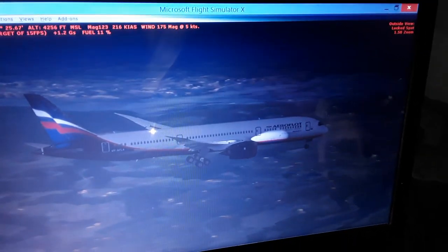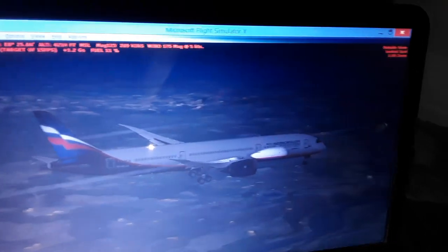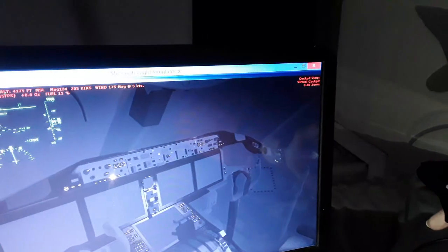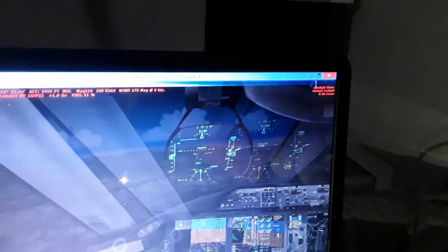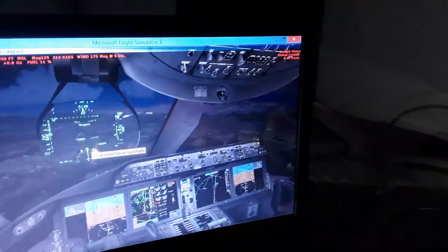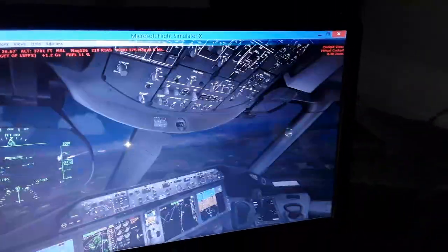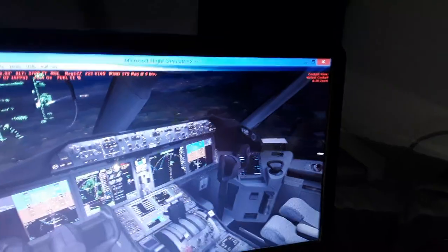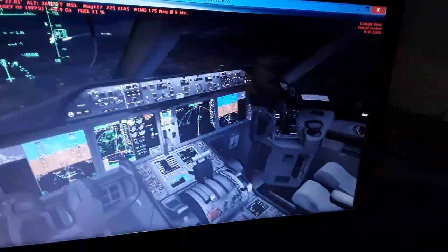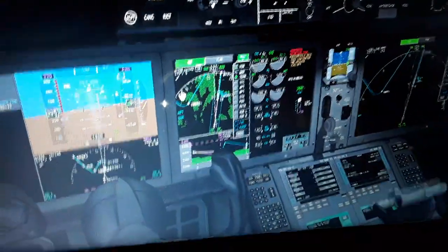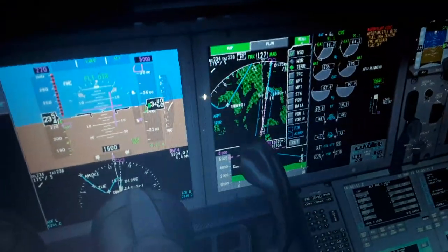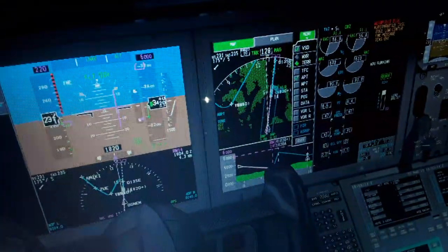So we have the aircraft, apply some thrust, the outside view we're gonna use for landing. So you can see we are aligned now with the runway, also full flaps over here. Also we have the LSZH localizer, the instrument landing system we need to use to follow the aircraft here, all the symbology, the airspeed and the altitude.